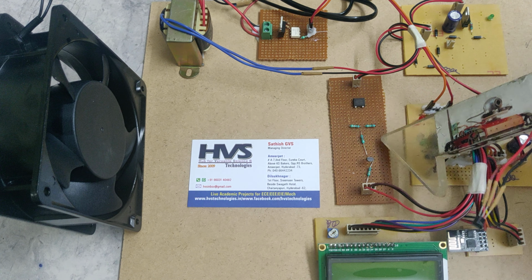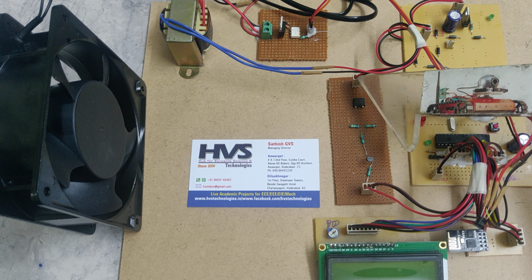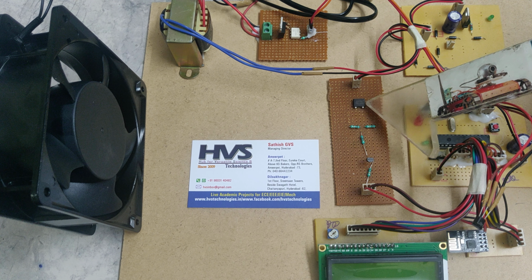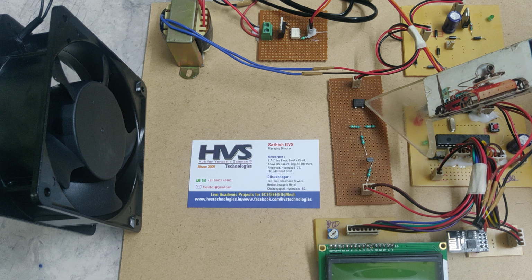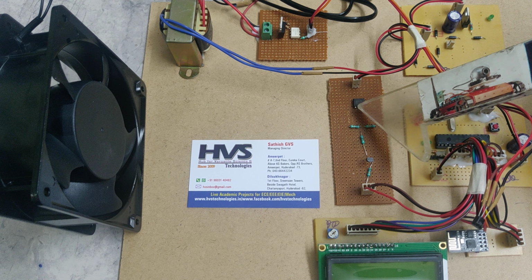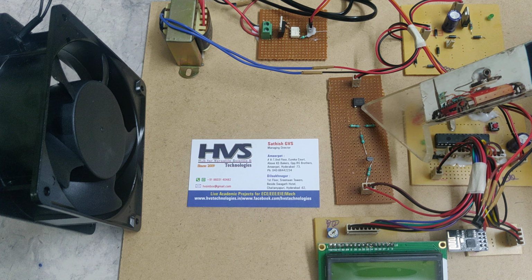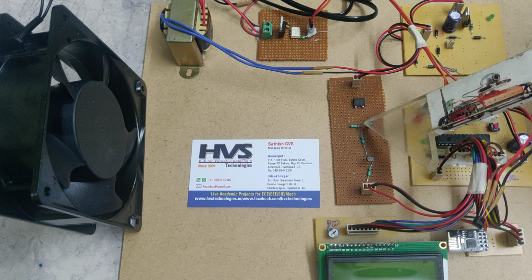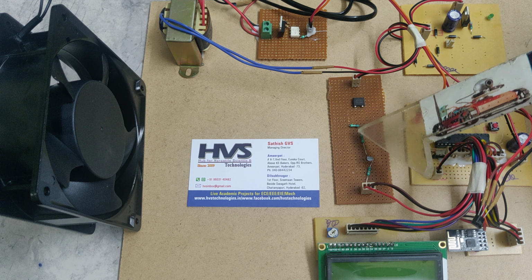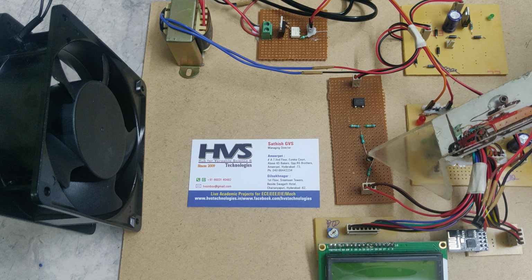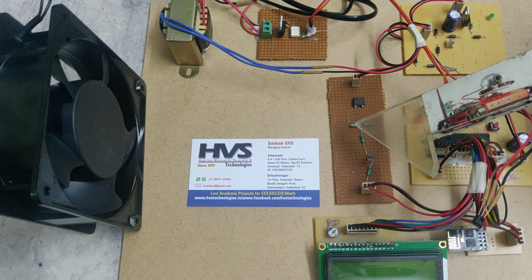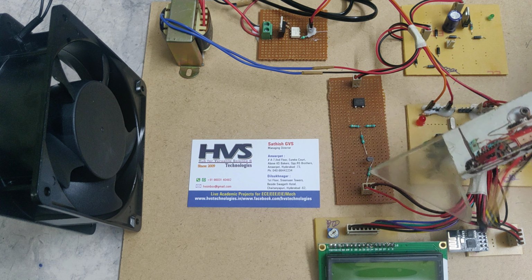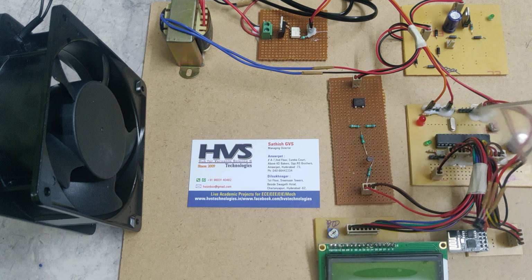microcontroller. And coming to this zero crossing detector, here we are providing AC voltage directly, which is the output of this transformer. We are providing the AC voltage input to this DB107, a full wave bridge rectifier. After this we will get a pulsating DC, and that pulsating DC of 12 volts will give an input to this transistor base through this potential divider circuit, and the trigger resistor is 1 kilo ohm. And after this the pulses will be given to the transistor, and the transistor will get switched on whenever the zero crosses the positive waveform, and then it will inform the microcontroller through these three wires, and the microcontroller comes